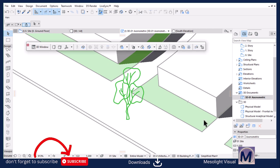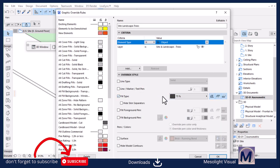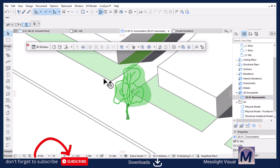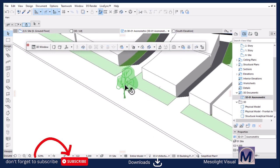Oh, I think I need to set the fill. I see where the problem is. Let's go back to the site and landscape rule, and then make sure the fill type is active, and then let's set it to 50%, and then make sure the cover fill is selected in the drafting fill. And we say okay, boom, there we go. We have a nice fill.